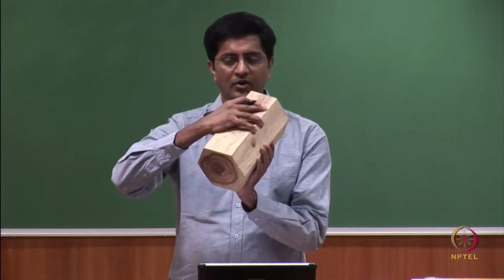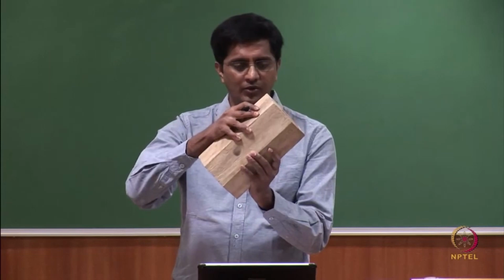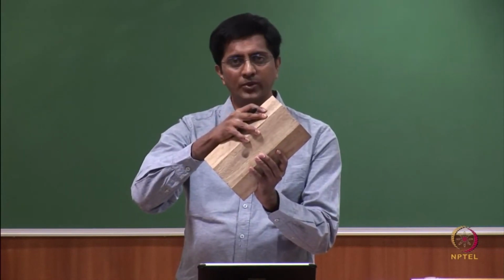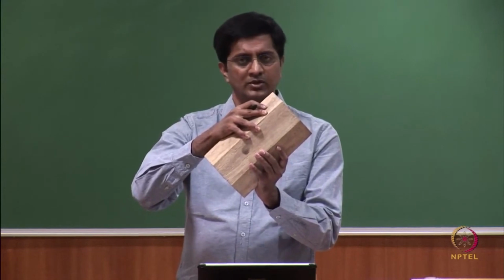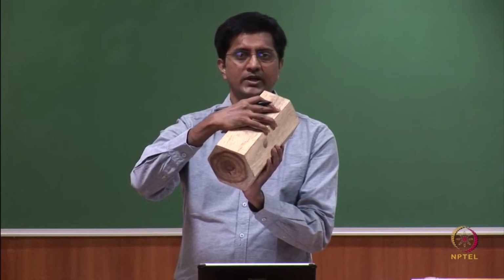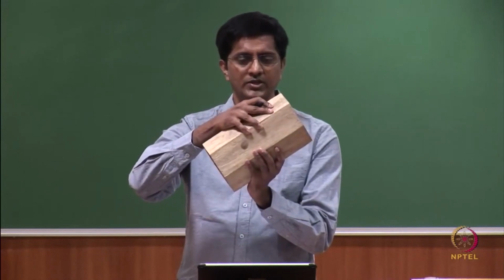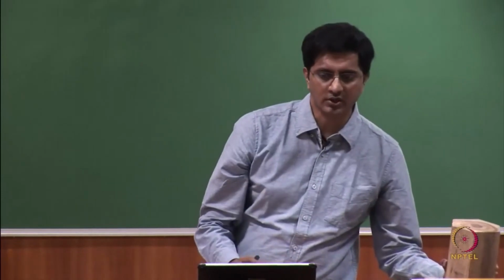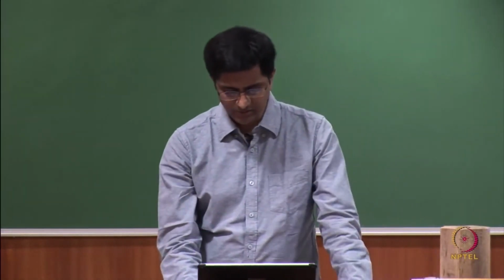So, before and after rotation, will the top view or the front view remain the same? So, I am not talking about the complete view, but the shape. So, if you notice clearly, the top view retains the shape, whereas the front view there is a change in shape. So, we will start with the top view for step 3.